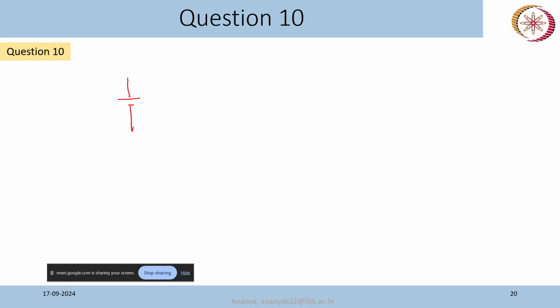So our circuit will be like this. We have some input voltage. There is R1, R2, R3, R4. Current is 0 means we can say that it is like an open circuit. In an open circuit, current is 0, right? So our equivalent circuit will be like this. And what is our input voltage? 12 volt.